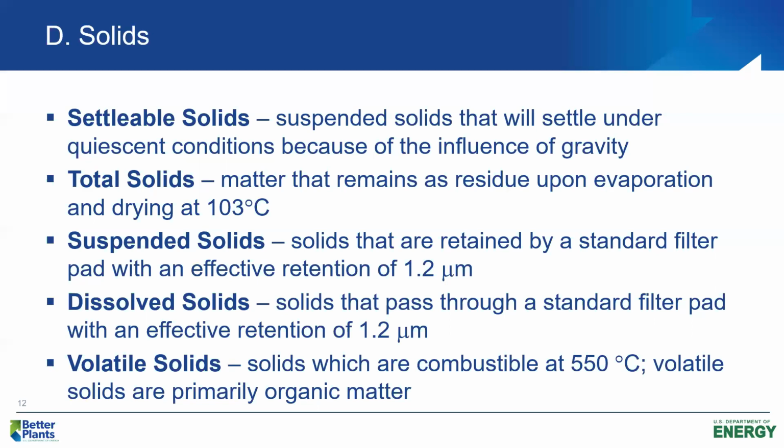So when we measure suspended solids, what we do is we use our standard glass fiber filter, which has a retention of about 1.2 microns. Take a known volume of the wastewater, we draw it through the filter pad, and so any solid larger than about 1.2 microns will be retained on the filter pad. The solids that are smaller than 1.2 microns pass through the pad, and those are the dissolved solids, but actually they're the dissolved and colloidal solids because they're less than 1.2 microns and they pass through the filter.